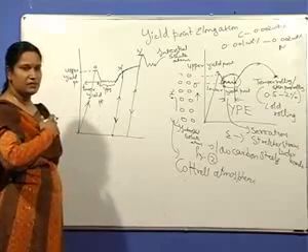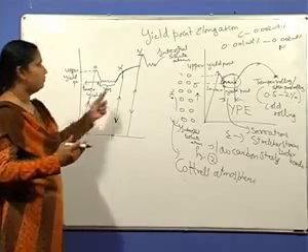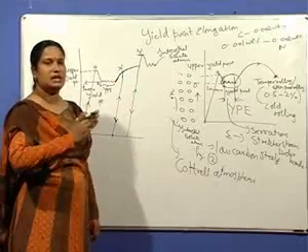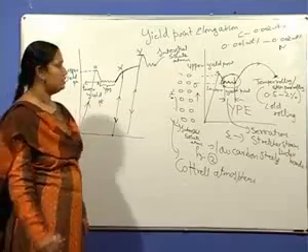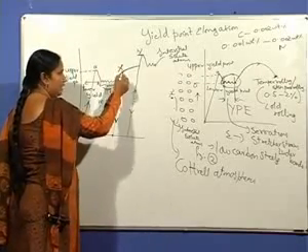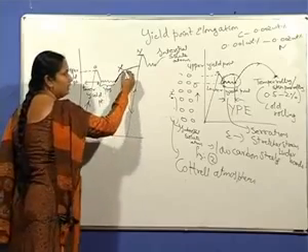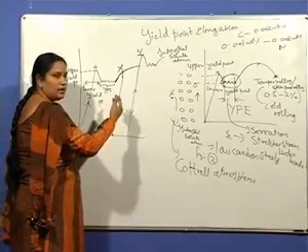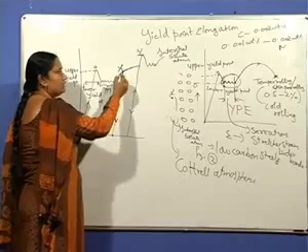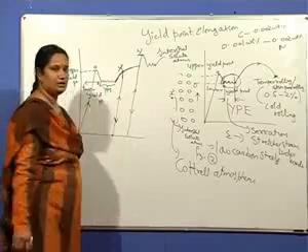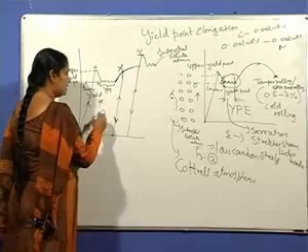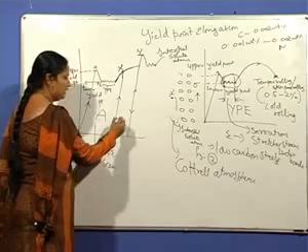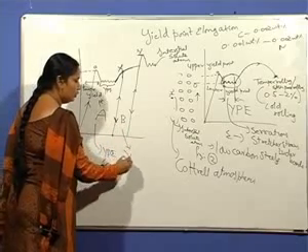Then once the dislocations are completely torn out from the atmospheres, strain hardening is observed. That means the curve follows the normal curve. Beyond point X, unload that material and again reload it immediately without giving sufficient time. You can see that there is no yield point elongation. So in region A, yield point elongation is seen, and in region B, there is no yield point elongation.